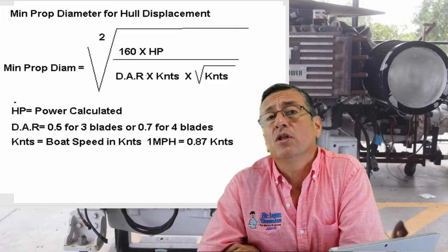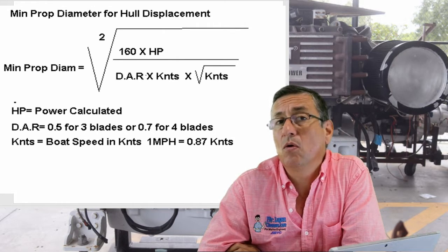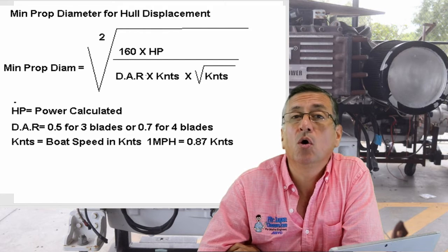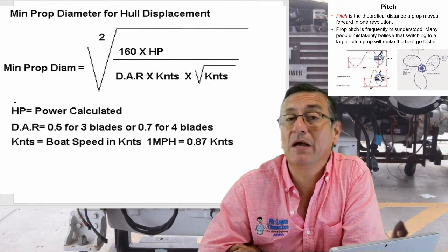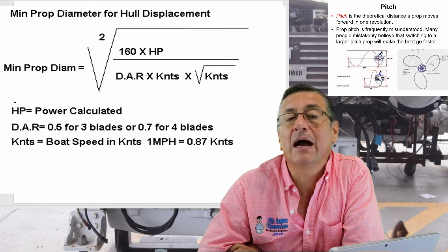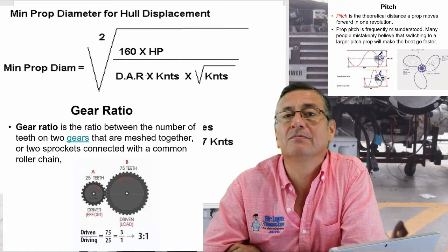How can I increase the torque? Probably with another propeller, one with one more blade, or a little less pitch on the propeller. Or another gear ratio on the transmission.